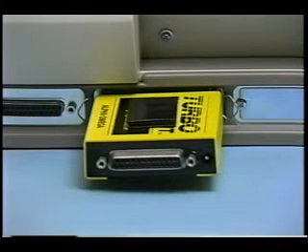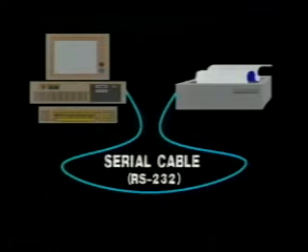It's very important to read and follow the directions in the manufacturer's installation literature before adding them to the data intercom. For StarBus to successfully connect any two devices, these devices must be able to communicate if attached directly together with an RS-232 cable between their respective serial ports. If a connection cannot be made without StarBus, it won't work with StarBus.